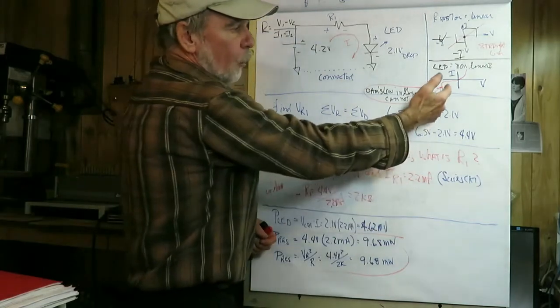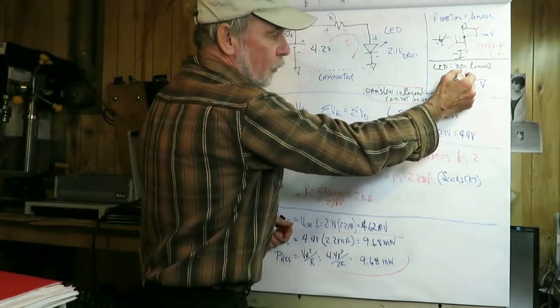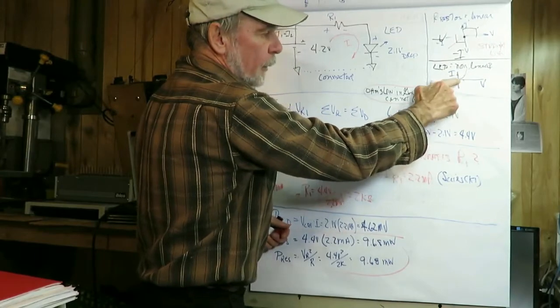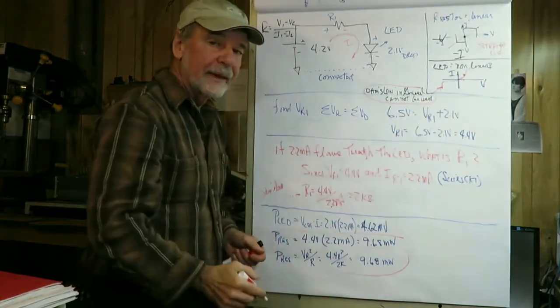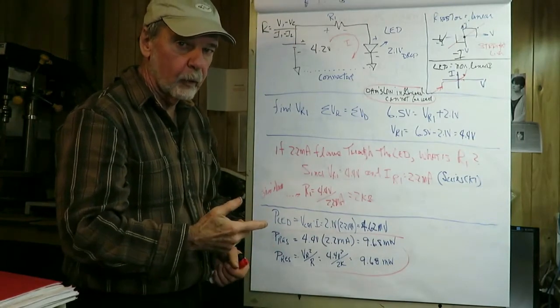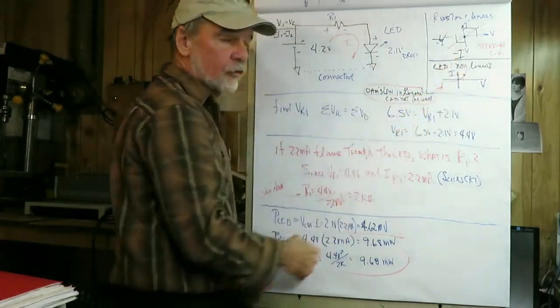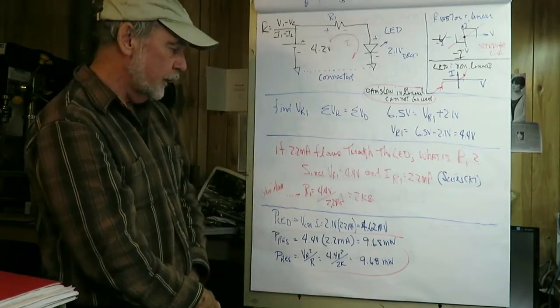But over here, what we could do is find the instantaneous resistance, which would be here and here, dividing V by I, but that would only be valid for that point. We could not, NOT, say that the resistance of the light-emitting diode is so many ohms, because it's going to vary. It is not a linear relationship. An important concept to understand.